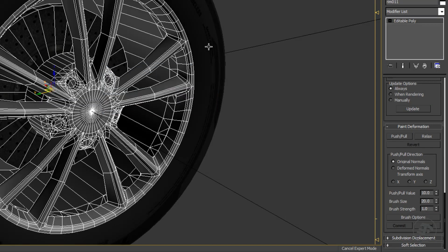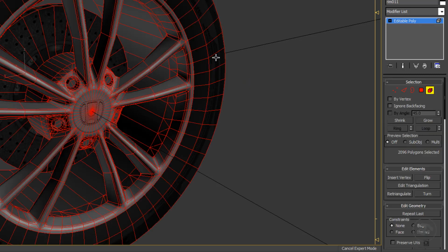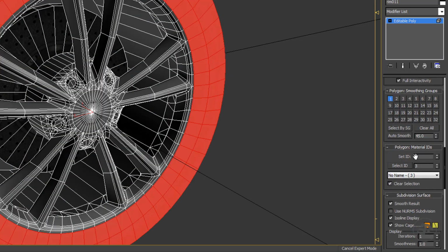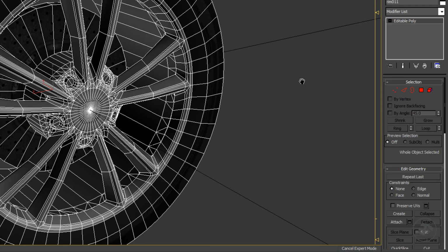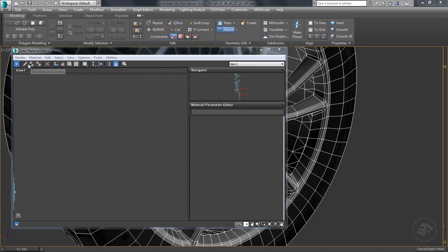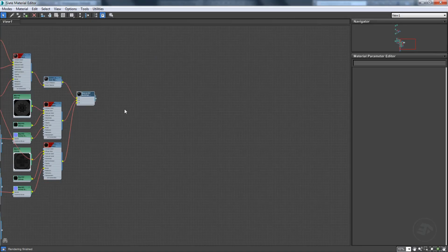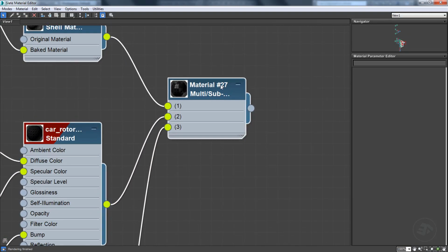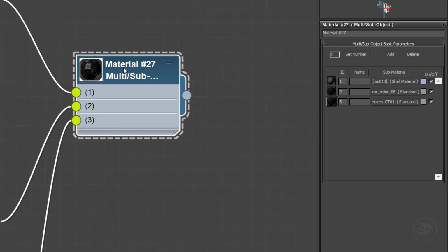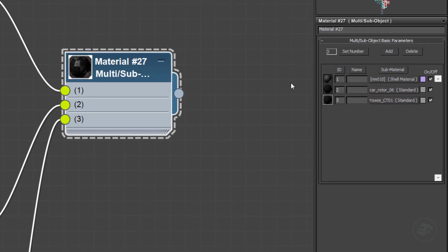When attaching multiple objects with multiple materials, 3ds Max will create a new multiple material for the newly attached object. Inside the Slate Material Editor, pick Material from Object to view the created multiple material. The polygons can store numbers to identify the material. However, only the object level can store the material name.